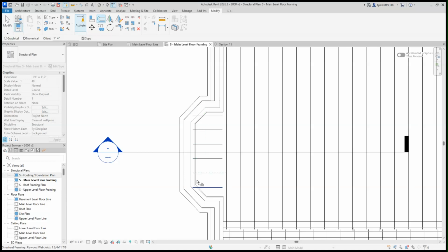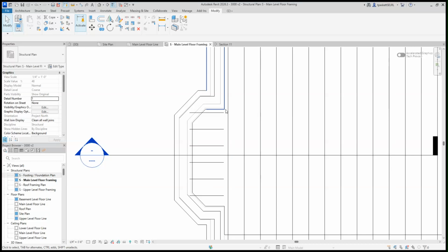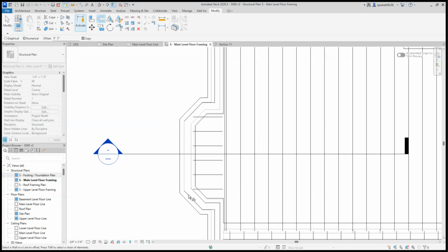And they don't have to be symmetrical. Don't worry about that. Now I want you to notice something. If you see how there's this gap here, what that's doing is implying that this is hung on the joist or on the beam, so that it's stronger. Because I'm doing this with them kind of perpendicular, I'm going to do an offset of 2 inches and take this 4 joists and double it up so that it's a little more weight.